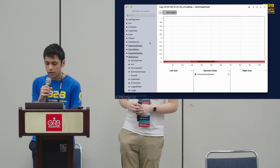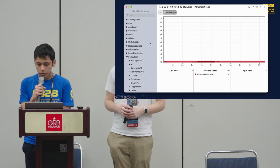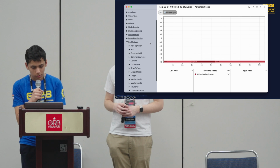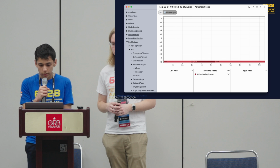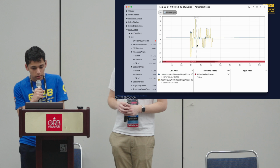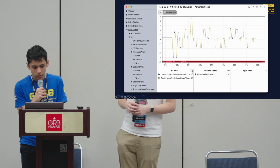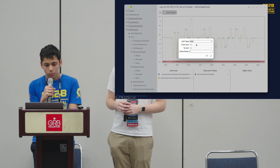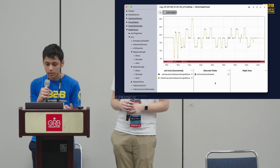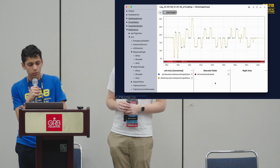First, let's go over how we might analyze the arm behavior through AdvantageScope. We'll pull a log from one of our previous events. In this example, we're going to pull out the measured and the set point angles for the elbow. We can zoom into the match to find the more relevant data right here. We've also included when the robot is enabled in the discrete fields. Here the units are radians. We might want a more familiar unit such as degrees because it's easier to interpret logs. We can see in this graph that the angle tracks pretty well.